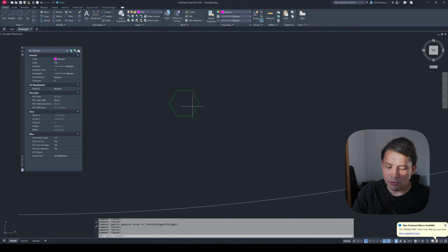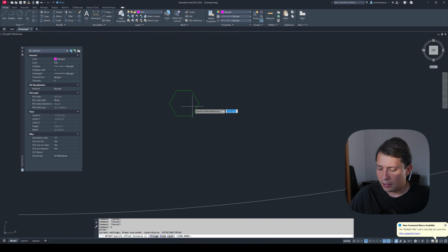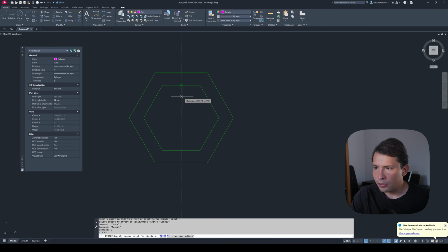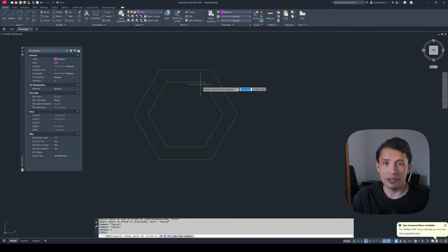And then I am going to create an offset to give a bit more detail. The offset is going to be 500 right here. And then inside here, just in the middle, I am going to extend from the midpoint, and we're going to talk about the snapping points very soon. So as you can see, this bollard has endpoint, midpoint, endpoint. These are called snapping points.